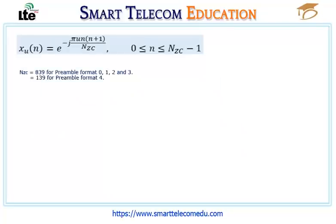The preamble is generated by Zadoff-Chu sequence, where NZC is the total number of Zadoff-Chu sequence, equal to 839 for preamble format 0, 1, 2, and 3. For preamble format 4, NZC equal to 139. The parameter U is derived from the root sequence index parameter used to generate the PRACH